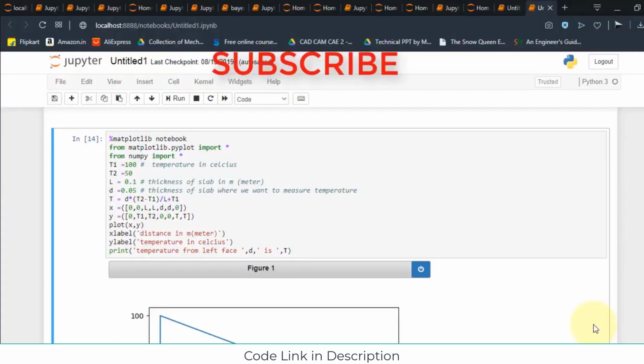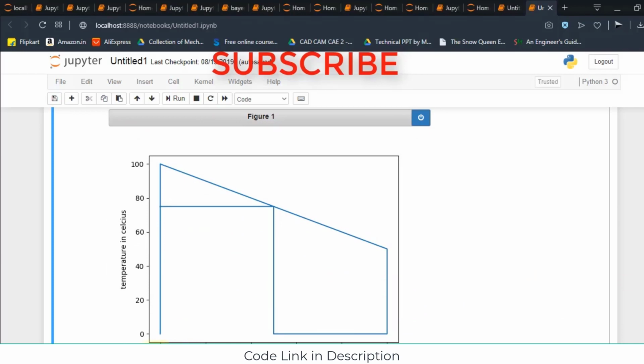Namaste. In this video, I will tell you how to plot the variation of temperature within a wall. This method is also called interpolation. The problem is that we have a brick whose thickness is 0.1 meter. On one side the temperature is 100 degrees Celsius, and on the other side the temperature is 50 degrees Celsius. Now somebody asks what the temperature is at a distance of 0.05 meter. So I am going to calculate this temperature.